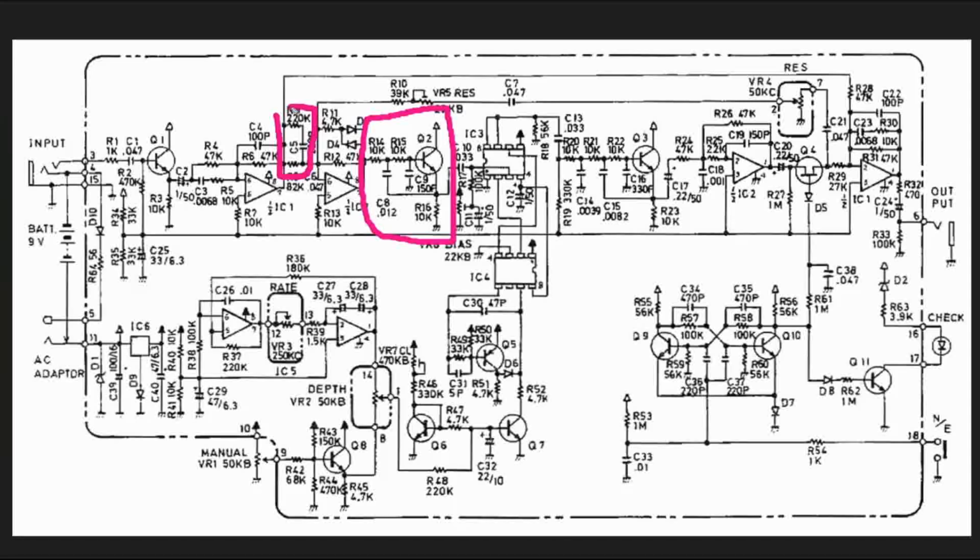Remember how I said that this is a single-pole low-pass filter? The reason for that is so that when we have this single pole combined with these two poles, that's going to act as essentially a three-pole filter. Okay, but this guy right here is rolling off the high frequencies so that we don't alias. This is our anti-aliasing filter.